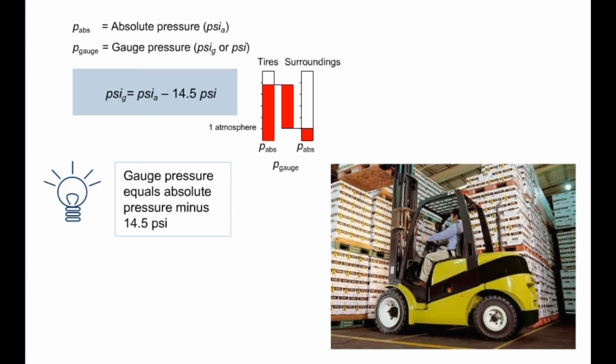The pressure values in the hydraulic cylinder and the tires of our forklift truck are measurements of gauge pressure. In other words, the absolute pressure in the hydraulic cylinder is, in fact, 3014.5 psi, whilst in the tires it is 64.5 psi. Occasionally, we come across the concept of negative relative pressure, for example in a vacuum cleaner. The relative pressure we are then referring to is known as negative pressure or pressure less than atmospheric pressure.